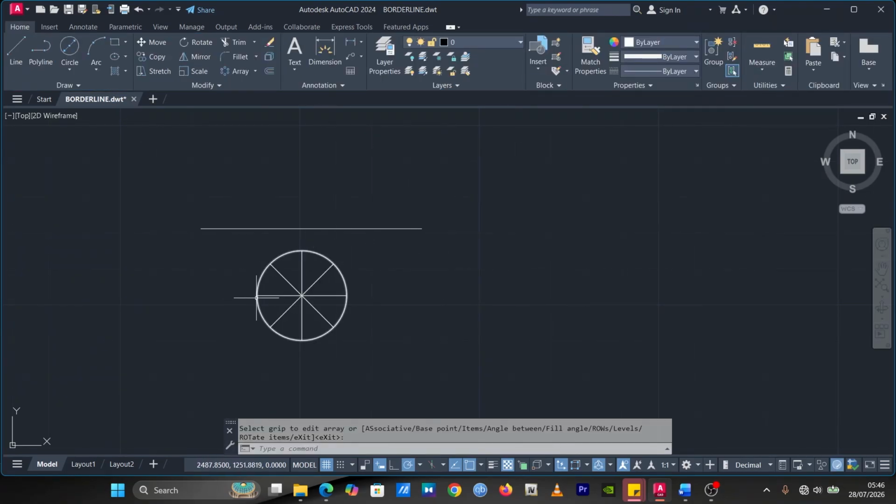When we are done, we are going to project this edge to meet here, and we project this edge to also meet here. So let's do that. We are going to have here, touching here. Make sure your line is straight. So it must be at an angle of 90 degrees, so meaning straight. So it meets here. Now we are going to change these two lines to hidden 2. Come to this side and you choose hidden 2. Good. So we are going to have something like this.